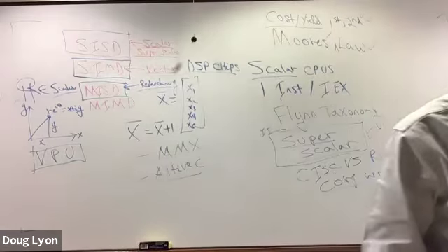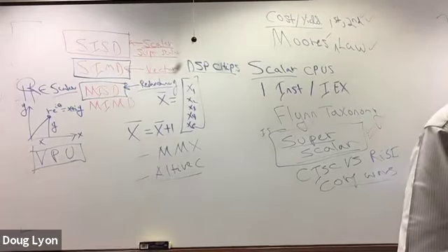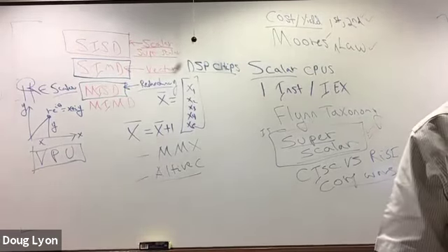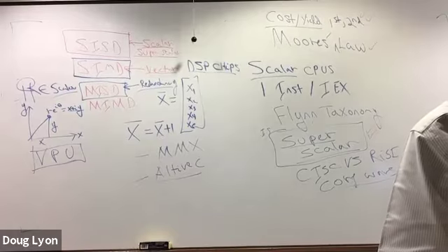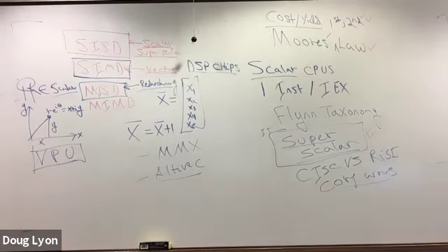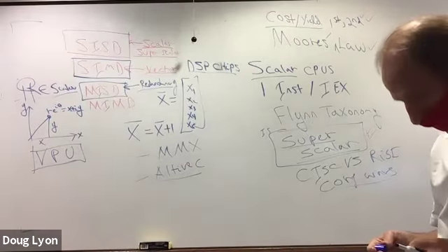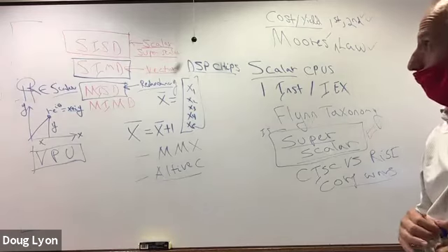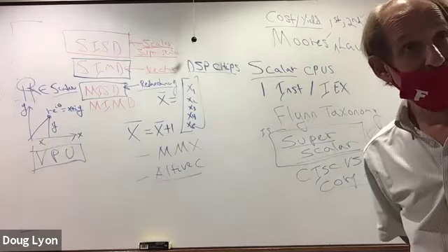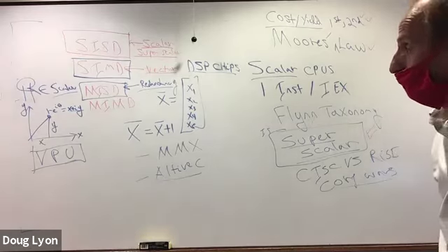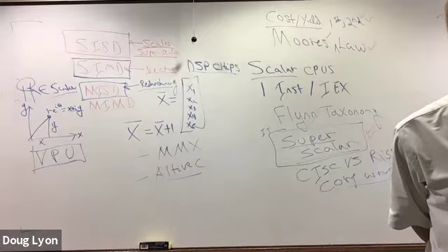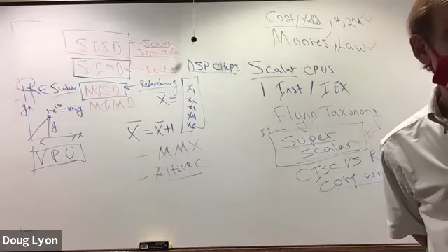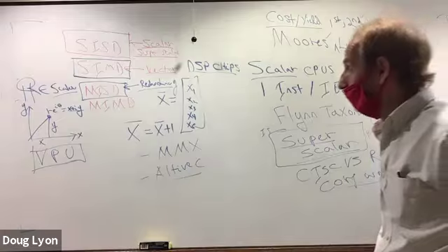In other words, if I had multiple cores all doing exactly the same thing on exactly the same data, I could have the cores check each other and make sure there aren't any errors. Why should there be errors? Well, if it's an aerospace application where you're deploying into deep space, you might have cosmic radiation messing up the flip-flops.